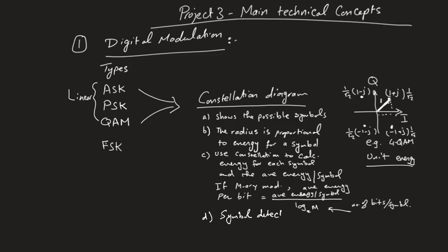Again, the whole idea, depending on your modulation, let's say, for example, your modulation was 4 QAM. We know that the possible symbols are the 4 symbols of the 4 QAM, right? But the problem is, after transmission through the channel, I might receive something like this. So I don't receive an exact symbol value because of the noise in the channel.